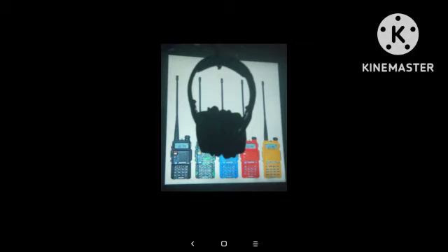Number 25. Approximately how long is each side of a cubical quad antenna driven element for 14.3 MHz? 5.36 meters or 17.6 feet. Number 26. The spacing between the elements on a 3-element Yagi antenna representing the best overall choice is blank of a wavelength. 0.2.